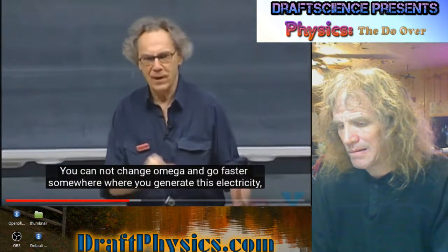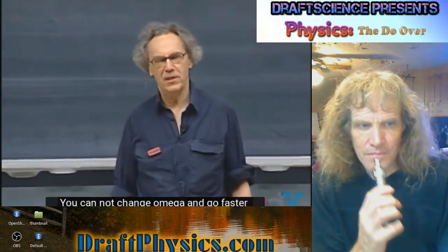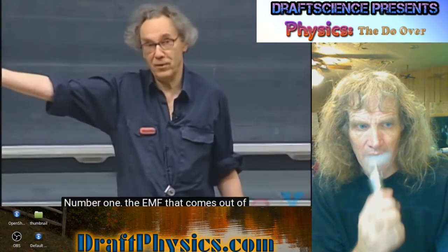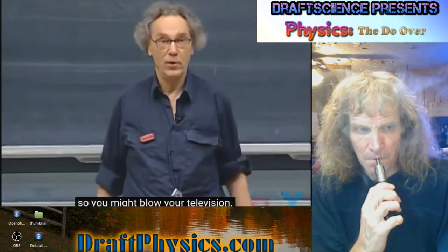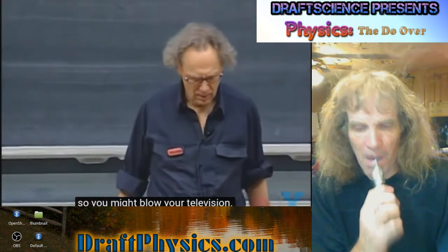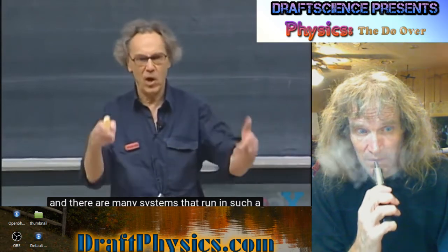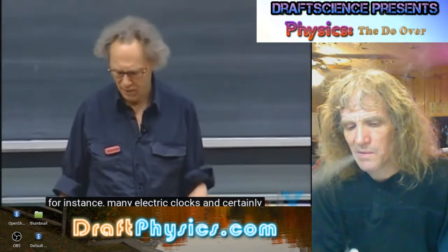You cannot change omega and go faster where you generate this electricity, because that would have major consequences. Number one, the EMF that comes out of the wall would go up, so you might blow your television and your circuits. But besides that, you would also change the frequency of the alternating current. And many systems are locked into that frequency. For instance, many electric clocks, and certainly record players, if you still have one, are locked into the 60 hertz. So if you were to increase omega, your record player would go around faster, and your clocks would go faster.